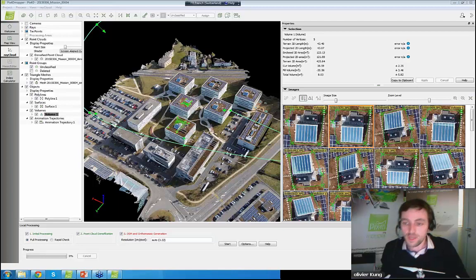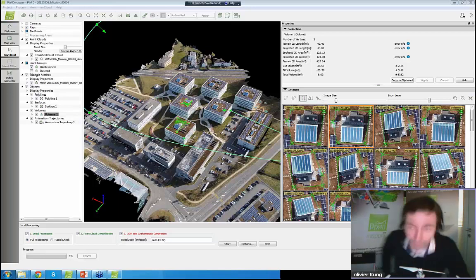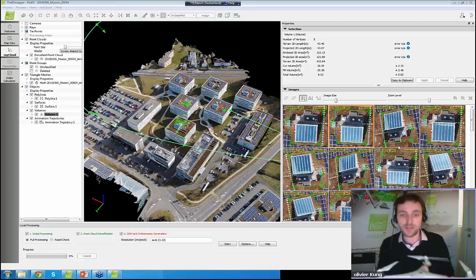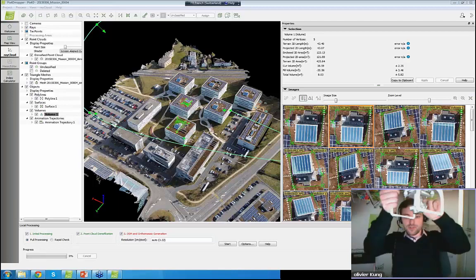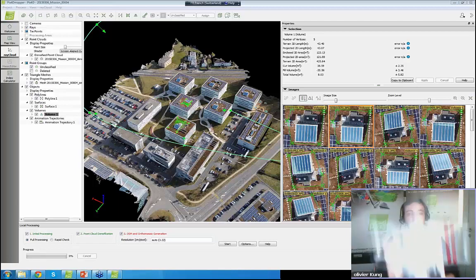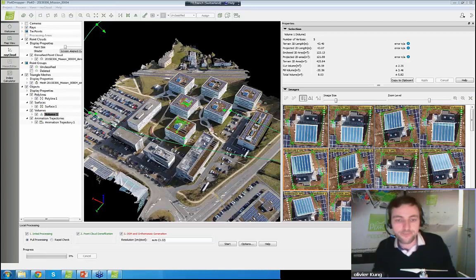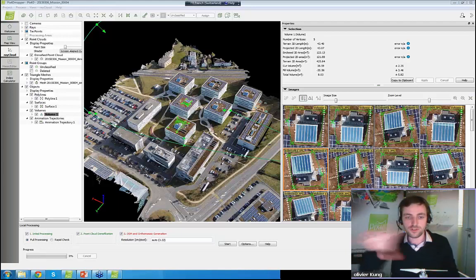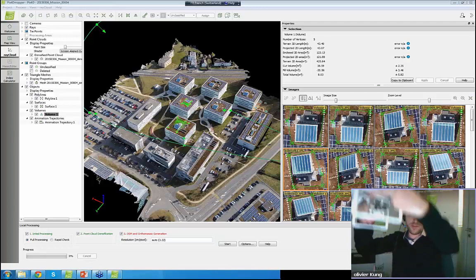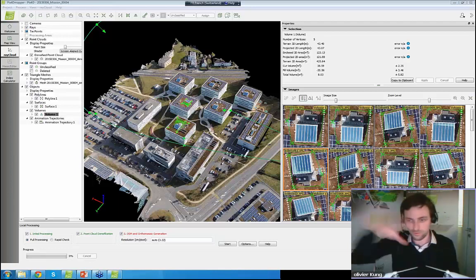Do you need to use the gimbal for better accuracy? No, a gimbal does not improve the accuracy of the 3D model at all. The only thing it does is make sure that the images are taken from the top down. However, if you also want to merge with free flight projects, to get better sides of buildings and so on, then it makes a lot of sense to use the gimbal, so you can rotate the camera to something like a 45-degree angle to your project.